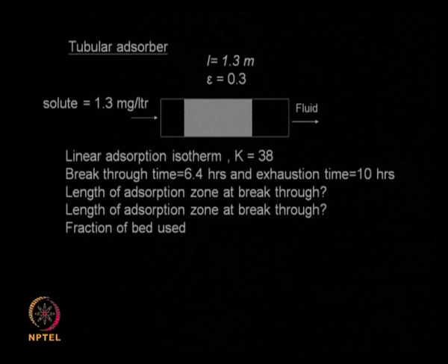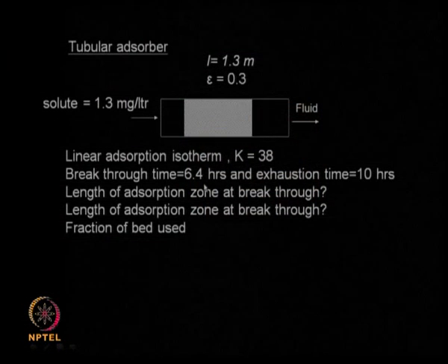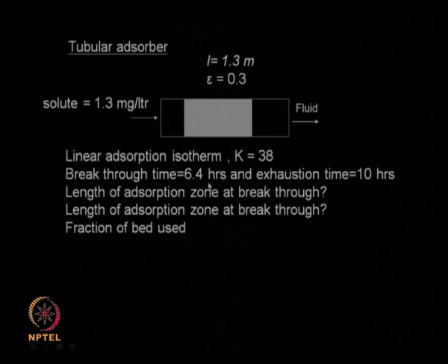And after some time the adsorbent is completely filled with the adsorbate. So it is not doing any job, whatever solute concentration is entering will be exactly leaving, and that is called the exhaustion time. Okay. So here in this problem the breakthrough time is given as 6.4 hours and the exhaustion time is given as 10 hours.